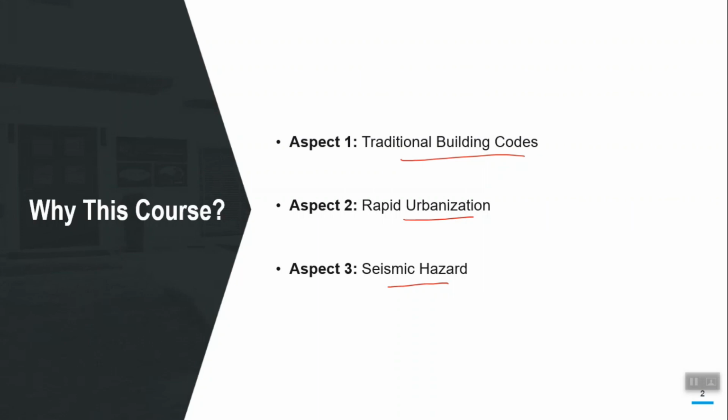Now, this can be extended to seismic design, but to other kinds of loadings also. For example, in wind load, the performance objective can be that at a thunderstorm of that much return period, or at that much level of wind loading, I want some minor damage only in my non-structural components, or I want the building to remain elastic under that particular level of loading. So, the idea that the performance objective is set by the client or building owner is applicable to any other loading also.